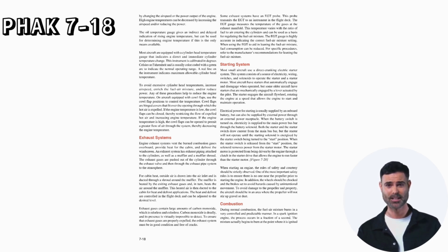The starter engages the aircraft flywheel, rotating the engine at a speed that allows the engine to start and maintain operation. Electrical power for starting is usually supplied by an onboard battery, but can also be supplied by external power through an external power receptacle. When the battery switch is turned on, electricity is supplied to the main power bus bar through the battery solenoid.